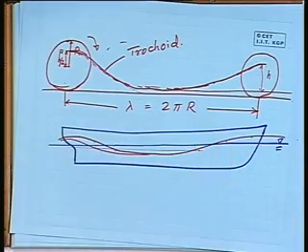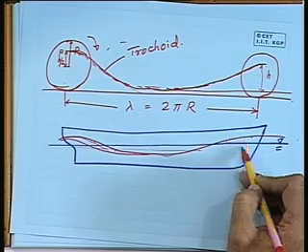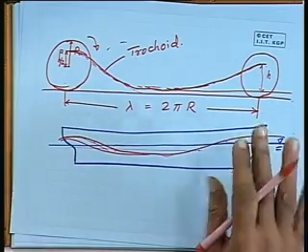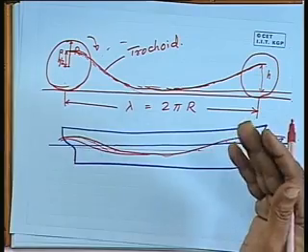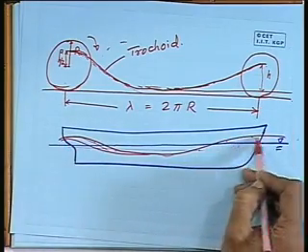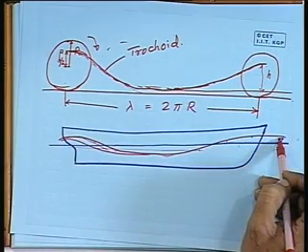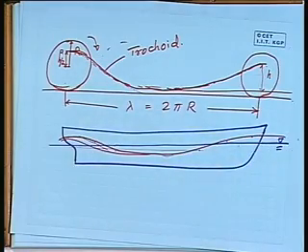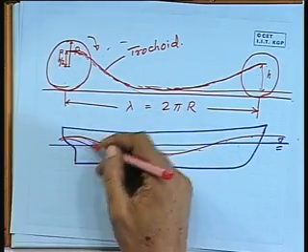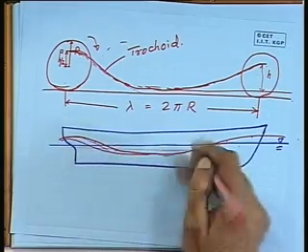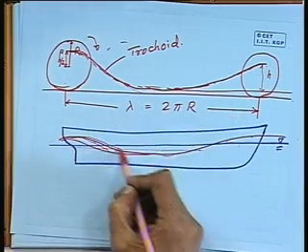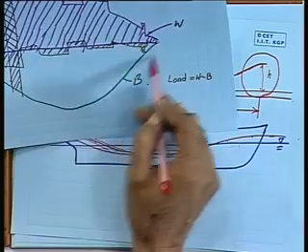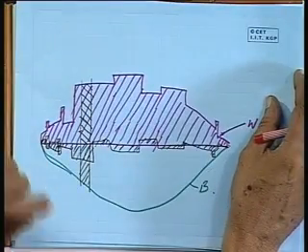Obviously there will be some difference because the volume here is more, the volume here is less, and therefore when you consider this way it may not match. So maybe 1 or 2 trials of calculation will actually fix me up to this position here. That itself is a detailed calculation, how to consider it. But once that is done, these ordinates of the areas submerged under this particular water height give me this buoyancy distribution.